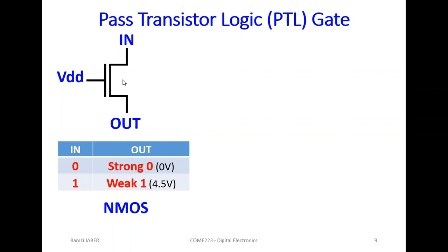So here we have internal diodes inside it. 0.5 volt will be decreased from 5 volt, so 5 minus 0.5 gives us 4.5. But 0 will not decrease by 0.5. We will not go deeply inside the transistor. Why does this happen? It's similar to a BJT transistor or something like that. We have internal diodes. If the input is 0, no internal diodes have effect.